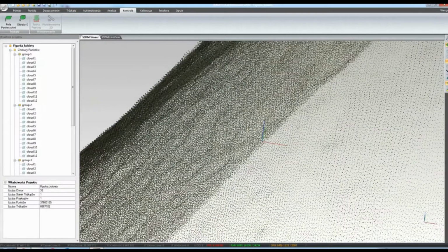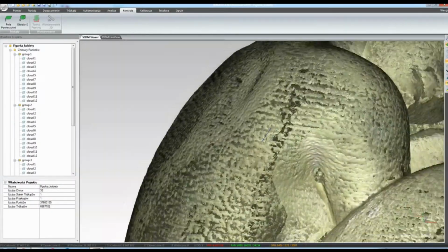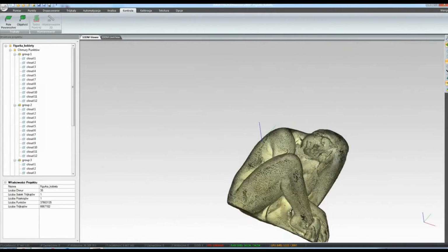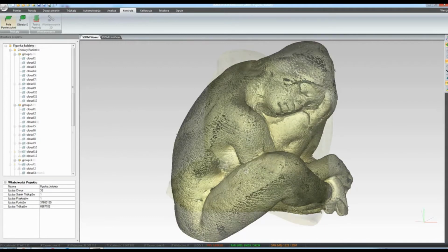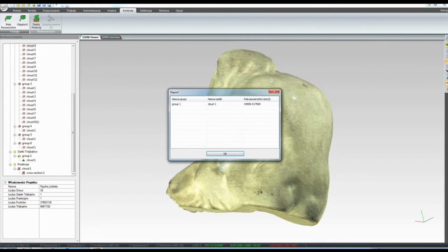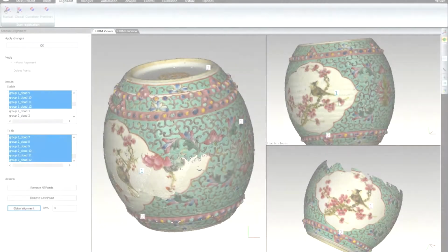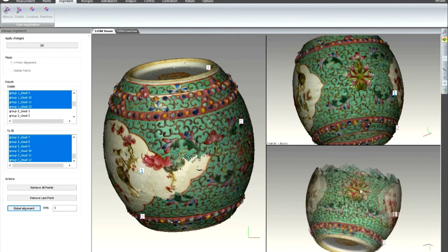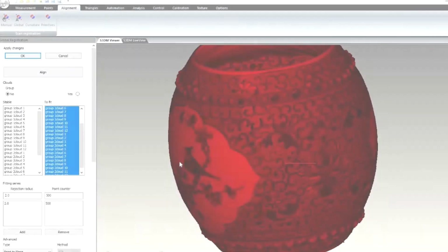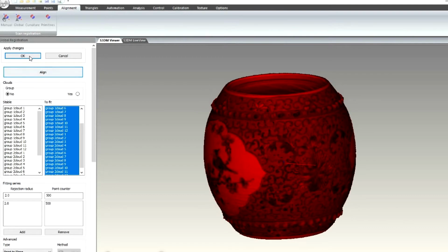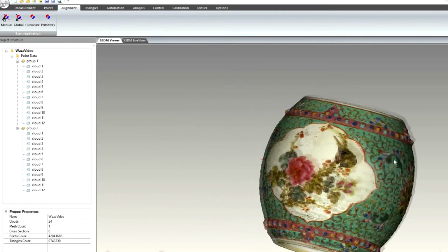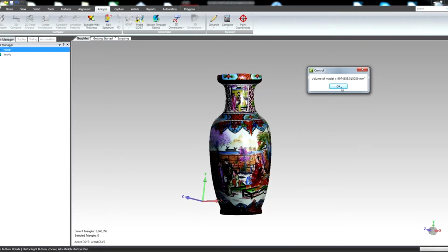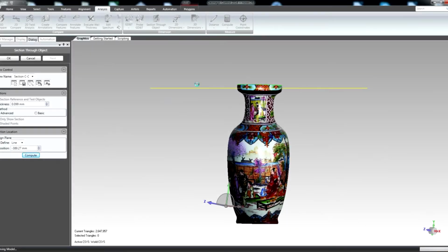As a result of the scanning process, we will achieve a cloud of points based on which the 3D model is generated. The line of Smartech 3D scanners dedicated to archaeology can register every point with the information about the color saved in the RGB scale. So the created cloud of points has not only determined coordinates, but also is colored, which can be useful in further research. The use of appropriate software allows to automatically transform the cloud of points to the metric 3D model as a triangle mesh, reflecting the color and the texture of the original object.